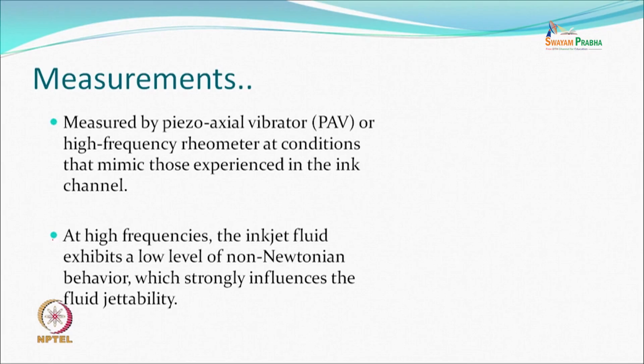And so, the measurements of viscosity, the method that we used earlier, may not be very suitable for this type of a material, because the ink is experiencing various types of pulses, pushes by actuators at very high frequencies, and therefore, the behavior should also be tested by instruments which work at high frequency.